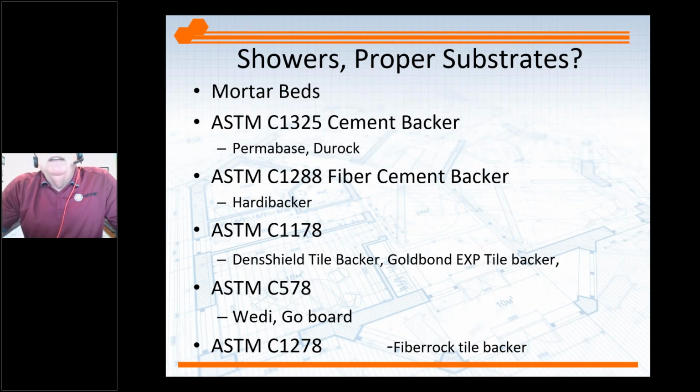It should be a different backer board. A lot of times there's confusion because the backer board names are very similar, or maybe they'll have the tile backer in there. But whether it's a Dens-Shield or a Gold Bond, they'll be using the Gold Bond throughout the house, and all of a sudden they're using Gold Bond. Well, it's a Gold Bond, yeah, but Gold Bond what? Or a Dens-Shield what? So it makes a lot of difference. You just want to make sure that they're using the proper backer boards in those shower applications.